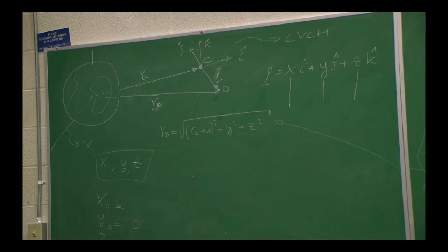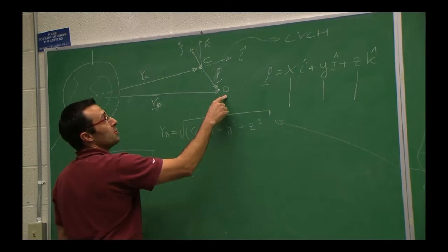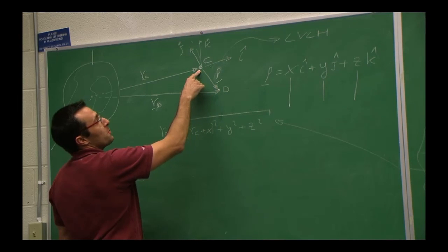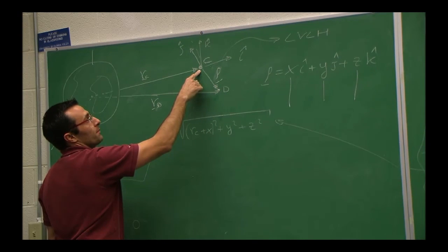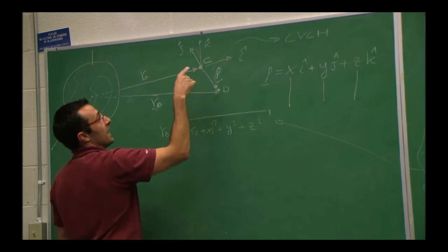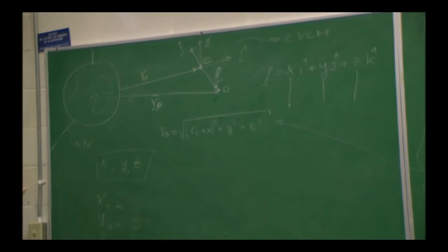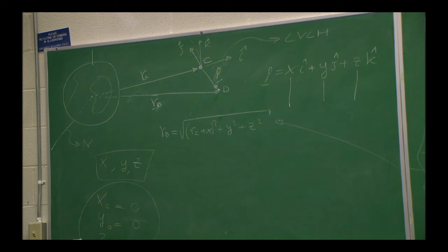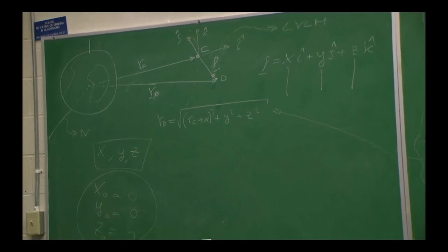First one is 0 as well, right? Again, this is the motion of this object with respect to this one. If my reference point is the chief, it means that my reference is at the chief. And when I am at the chief in LVLH, I am 0, 0, 0. Make sense? So this is important. You need to know what values you're going to introduce into the partial derivatives that you're going to compute.